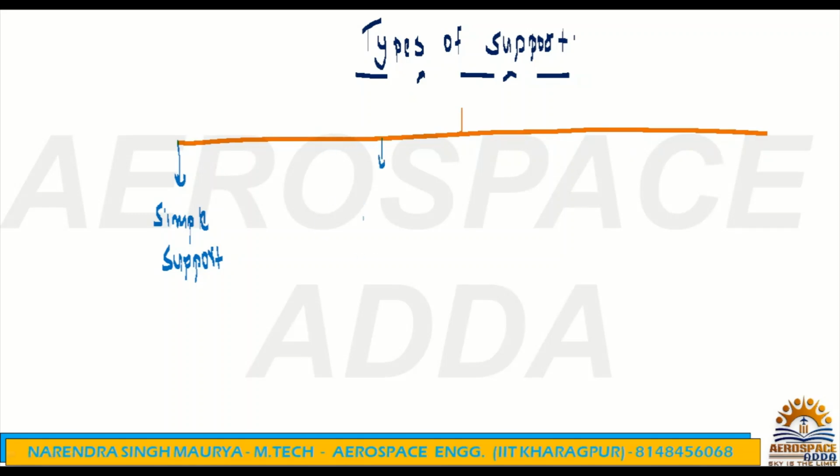First simple support, then we have a roller support. By the word only you can understand roller support. In this case, the beam end is supported on rollers. Obviously, if it is supported on rollers, then one roller will roll, and your beam can also move horizontally, but vertically that will not be possible. I will show the diagram, then it will be more clear. It is free to roll, so obviously it's frictionless. This is the second one.